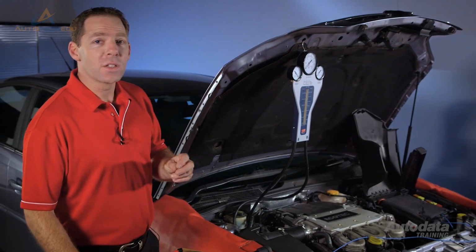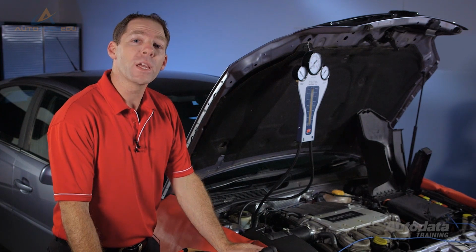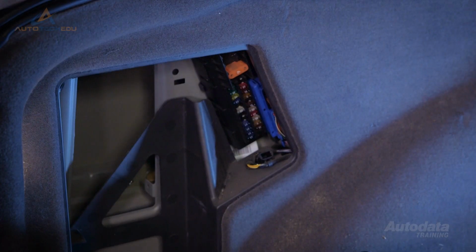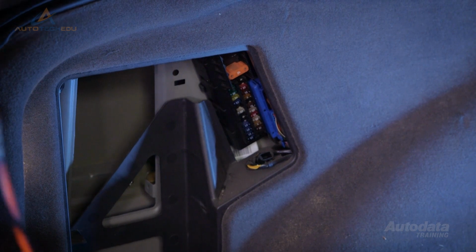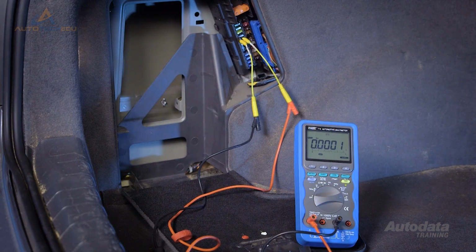There are several ways to test a vehicle's fuel pump electrical circuit. The selected way will depend on the type of fuel delivery system the vehicle has. The easiest and fastest way to test a fuel pump circuit is with an amp meter. Remove the fuel pump fuse and insert the meter. Enable the fuel pump circuit by either cranking the engine, using a scan tool, or bridging the fuel pump relay.